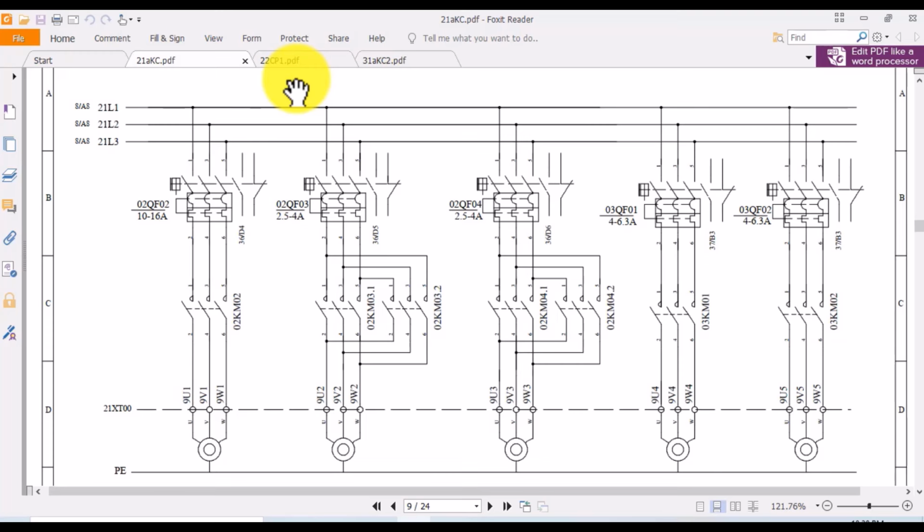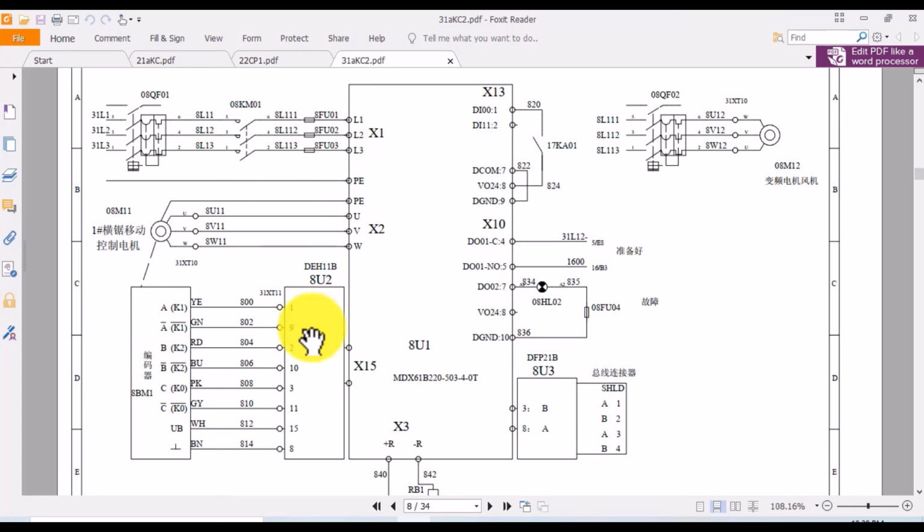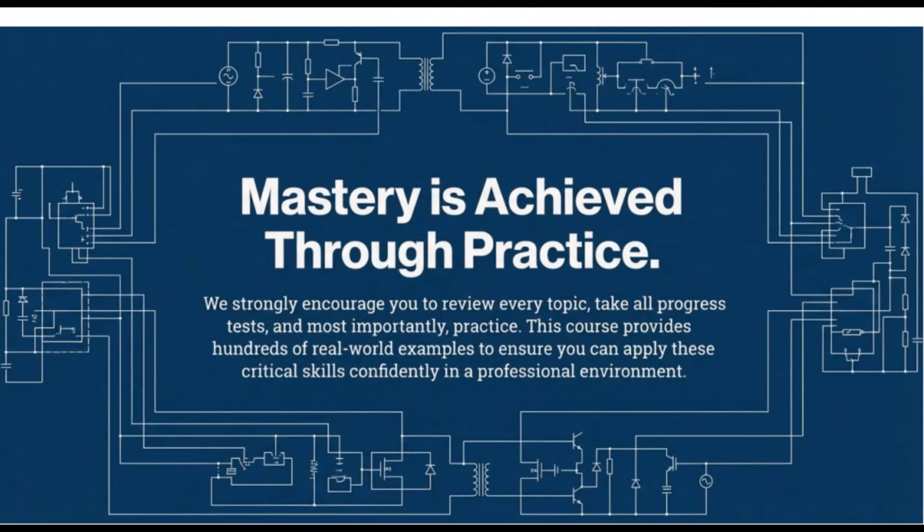And we're talking about everything from a simple push button to really complex devices, things like VFDs, variable frequency drives, which manage a motor's speed and torque. So for a VFD, what kind of data does the drawing need to capture? It's got to be more than just a symbol. Oh, yeah. For a VFD, you need to know its control voltage, what motor it's tied to, its capacity, and critically, how it fits into the whole system's logic. And that leads right into a core structural idea that the material really emphasizes, the concept of parent and child components.